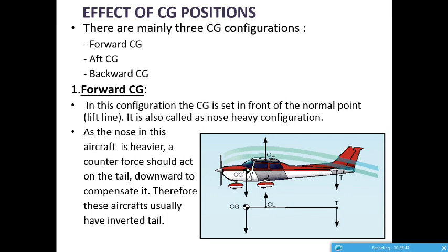So what is stall speed? We already discussed stall angle in some last slides, so now let's discuss in brief about stall speeds. Stall speed is the minimum speed that the aircraft can achieve without causing stall on the wing. Usually the stall speed for this forward CG aircraft is less, which means it's a disadvantage that it cannot fly very slowly.